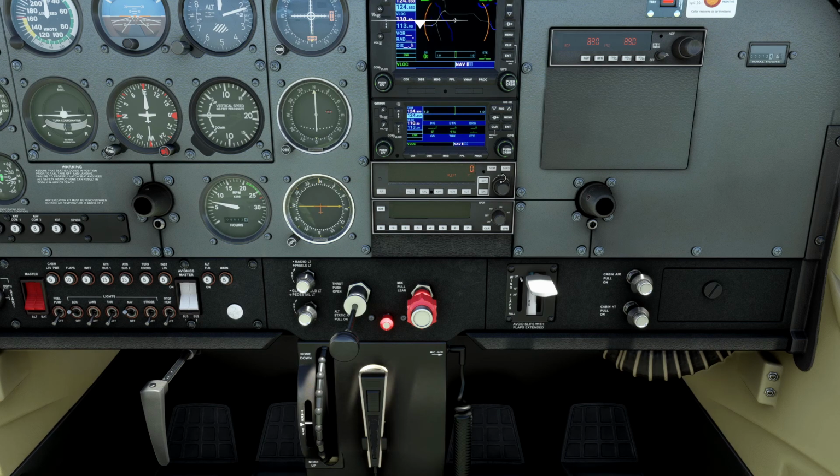The altitude pre-select function is pretty straightforward. The big knob is thousands of feet, and the little knob is hundreds of feet. So you can set it like that, and like I said, it just serves as a reminder and gets you set up. It's also a good idea to have the heading bug set up to runway heading. The heading bug works pretty straightforward. Just roll it to the heading that you want, and that's the heading that the autopilot is going to fly. So put it either to runway heading or the heading that you think you're going to use once you get airborne and are going to want to use the autopilot.